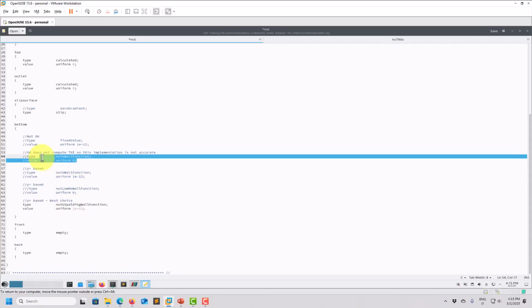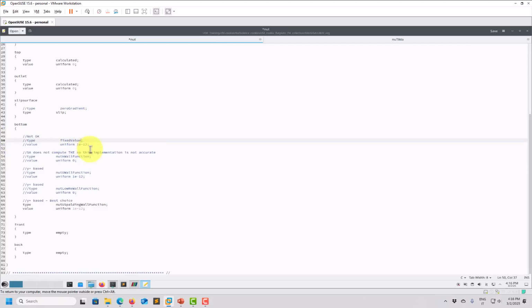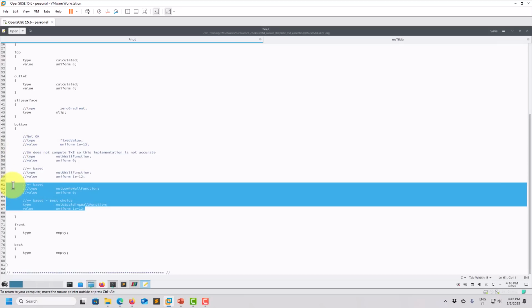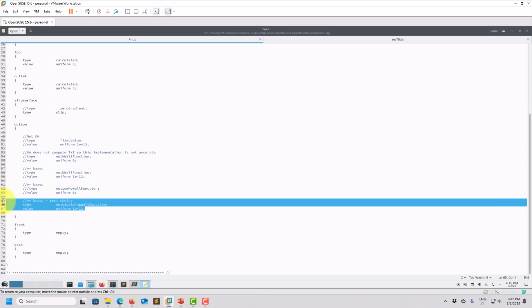This one is going to run the simulation. Actually, I think with the actual implementation, it should crash immediately because you don't have that quantity, but it runs. I recall that in an older version it crashed. Now it runs, but the results are going to be wrong, and you can entirely disable that wall function, but the results also are going to be wrong. So this is it, okay? Wall resolving, you can go for any of these. Personally speaking, for wall resolving, my best choice would be not Spalart.